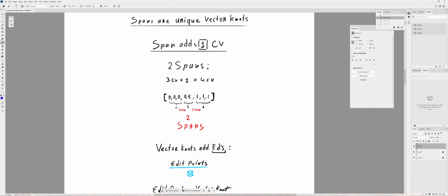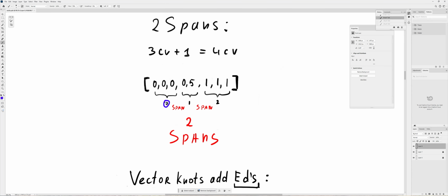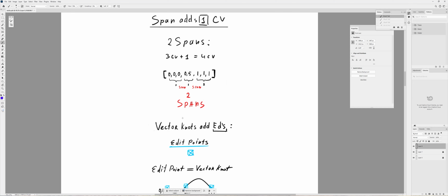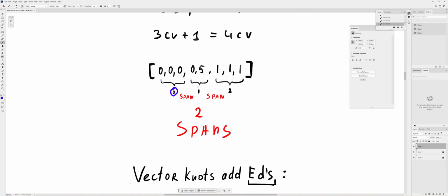These unique numbers like 0, 1, and 2 actually are represented in the interface of Alias. Rarely in other systems. It's mostly in surface modeling tools when you really need a lot of control. Other tools like Rhinoceros, or especially more modularized CAD software like, I don't know, FreeCAD, for example, don't do that. Or maybe, I don't know, Moi 3D. So these edit points mark these values on your curve.